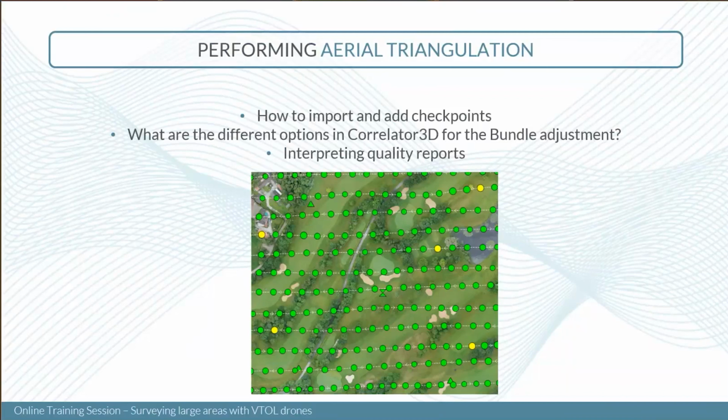It allows you to post-process all your raw data to get the best and most accurate data as possible. So the exterior orientation that you will import will be the one that will be done after the geotagging of the image. You will also be able to play with the calibration of your sensor in order to eliminate all the radial distortion of the camera, for instance. If you want to assess the accuracy of your aerial triangulation, you will probably need to use some checkpoints, as I was mentioning.